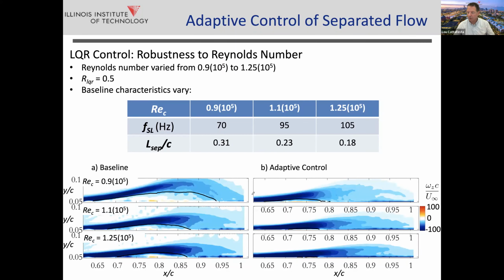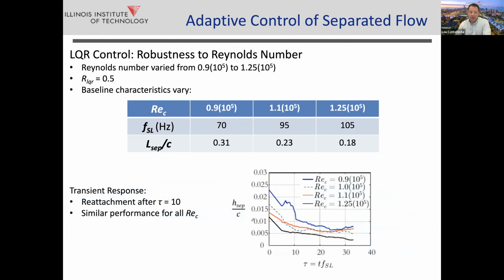And then when we turn on the control, again, we just turn it on, 0 initial conditions, all random values, and it establishes control. And indeed, in the higher Reynolds number case, it completely attaches the flow. And so the behavior, it's quite robust. You control, we don't have to sit there and tune this and run experiments for any extensive period of time. There's no knobs to adjust, just does this on the fly. And the performance is basically the same in terms of its transient response.